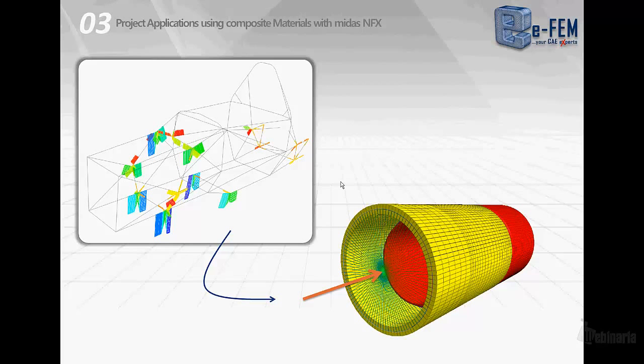So we extrapolated from the global model the normal, transversal, flexural and torsional loads on the frame, and we applied them near the bonded joint. We applied these actions directly to the local model by means of a rigid element spider, in order to be able to apply these loads to a single point.